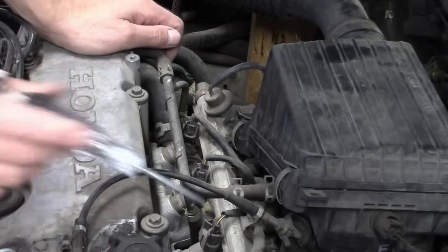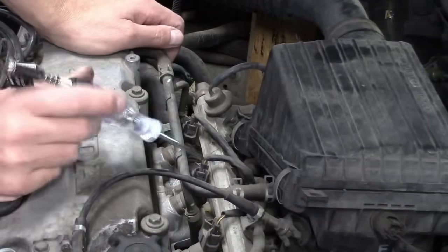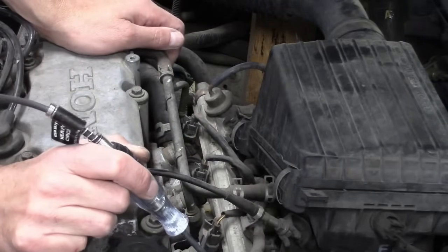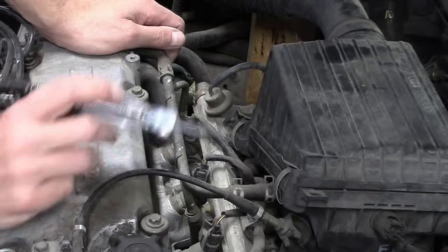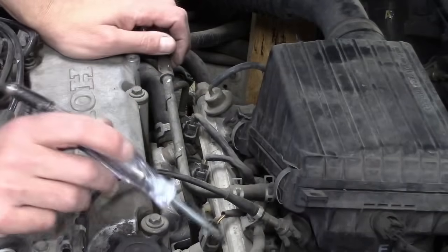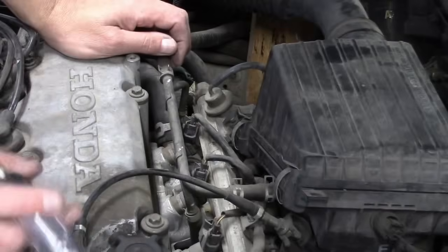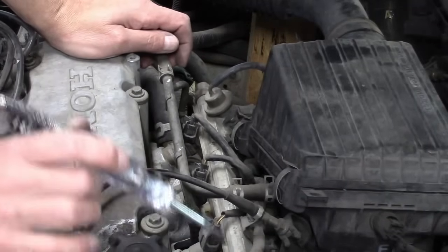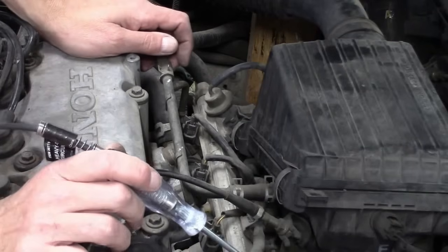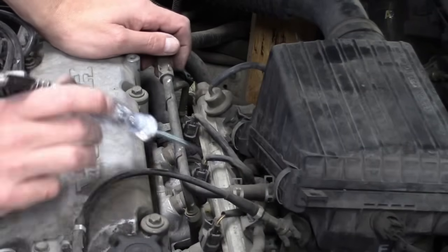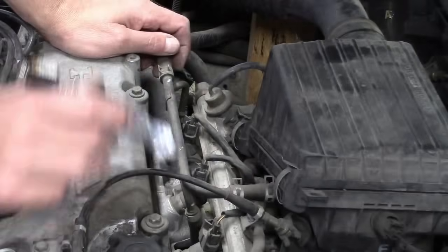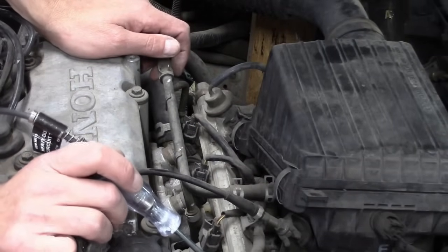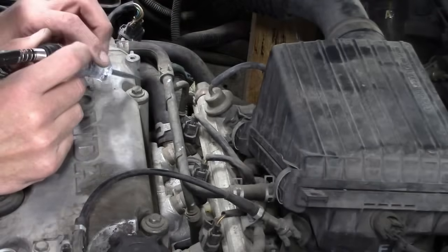And what that's telling me is I know where the grounds are because the wires that are the same color, that is going to be a constant power feed. The different colored wires on each injector are going to be the ground, respectively going to PCM terminals. Now, maybe I'm wrong about that. I've never seen a fuel injector that was power side controlled. Even so, if that's the case, it would be the other way around. The yellow with black would be a constant ground on all injectors, and there would be different power feeds turned on each time at each injector. I doubt that's the way it works.